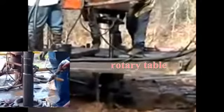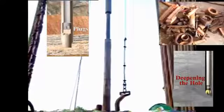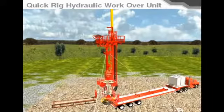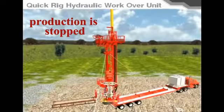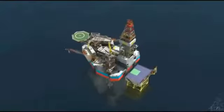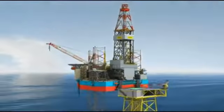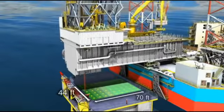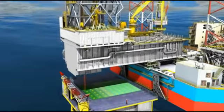A rotary table and a reverse circulating mud system can also be attached for drilling out plugs, junk, or for deepening the hole. These pulling units work with the tree removed, so flowing wells have to be killed, which means that production is stopped. The last one we mention here is not a workover rig, but a conventional drilling rig. The drilling rig that was first used to drill the original holes on deep water platforms is left in place to later act as a workover rig.